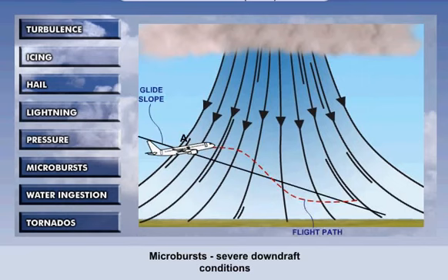An aircraft on approach or takeoff can experience the following effects. Strong headwinds at this stage causing an increase in performance and airspeed. As a result, the pilot will reduce power to maintain the speed and lower the nose to recapture the glide path.